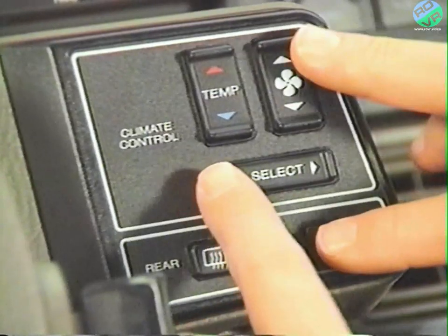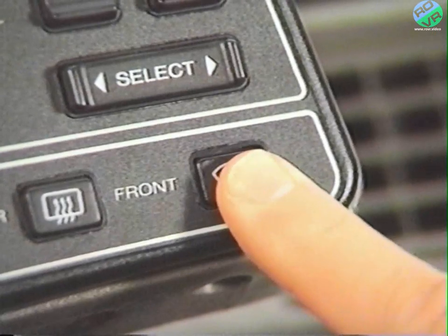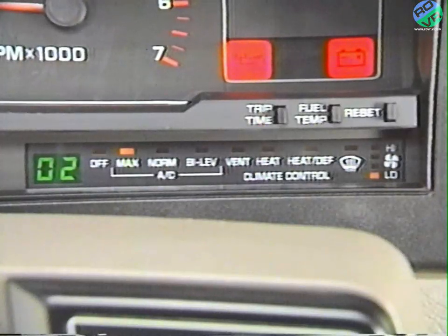Simply enter the mode at which the fault was discovered, low or M1, and press the front defrost switch for 5 seconds. The mode light which indicated the error will flash while the switch is depressed to indicate the fault clearing attempt. If the cause of the fault has been corrected, the mode light should go out when the front defroster switch is released.